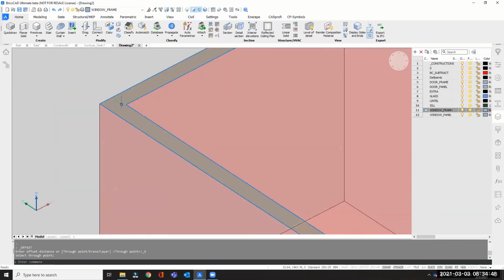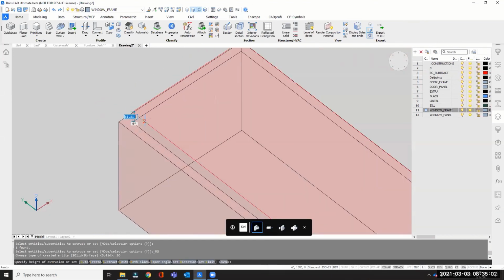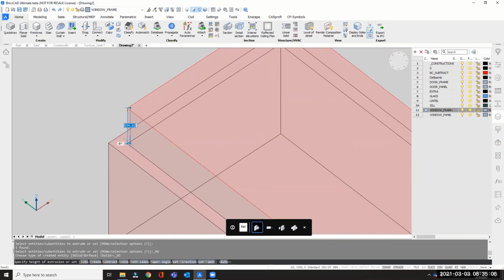And what we want to do is actually the frame, right? So let's go to the outer boundary and go into our quad, and you'll find a solid extrude that's already there. Let's extrude this, and you would find that when you extrude, it's actually subtracting parts of your solid, but that's not what we want to happen. We want to create a frame that's also going to be visible, right?